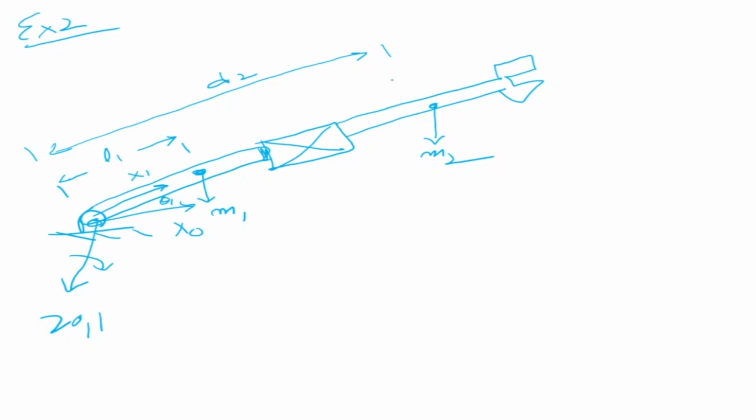Okay, so we have two variables, and this is a 2-degree of freedom system, 2DOF. We have put DH parameters, so note this very, very carefully. Where are the axes and what are the two variables? Now we need to understand very carefully where the second z is. Second z is this side, z2. Okay, and x2 can be put here.